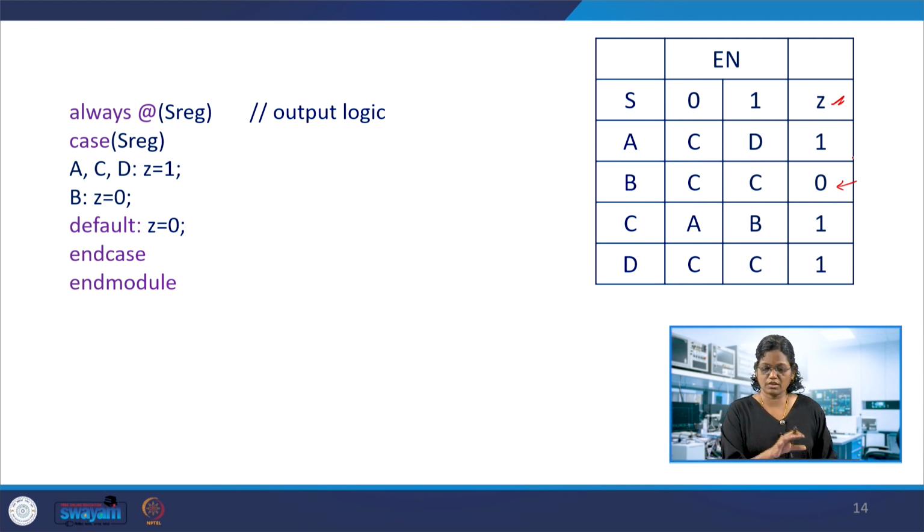So once we have the digital circuit and the state transition table along with the output, the code can be written with 3 always blocks, 1 for the state memory and another one for the next state transition logic, and the output can also be written this way.